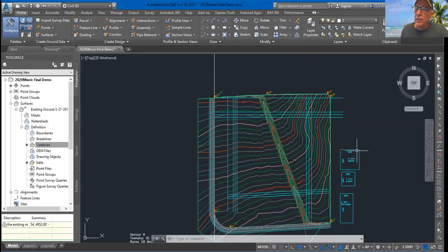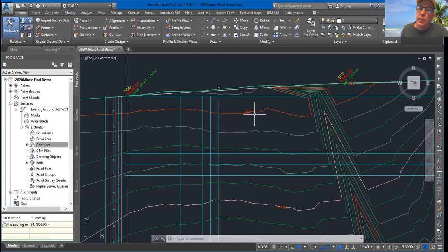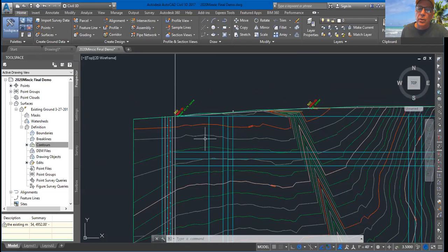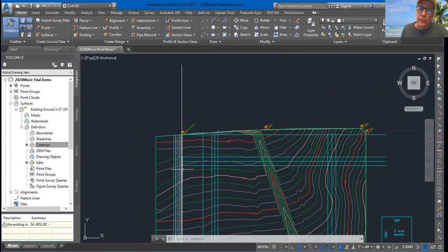So using my information over here, I do know that 208 feet is the minimum distance I would need to get a square lot. So what I have simply done is I've just drawn an arbitrary line here, starting about right here, and I've offset it 208 feet. That's the distance between this line and this line. That gives me an idea that I could make some square lots along the top right here. And over here, I've made a 208-foot line also.